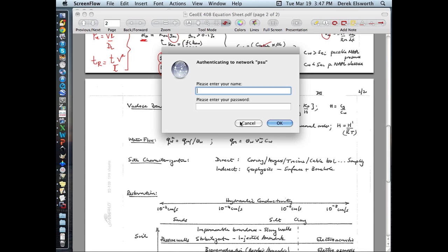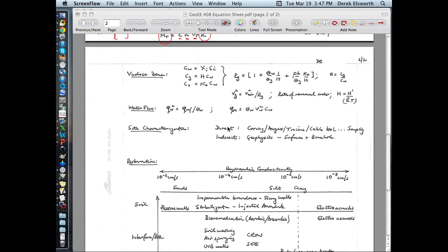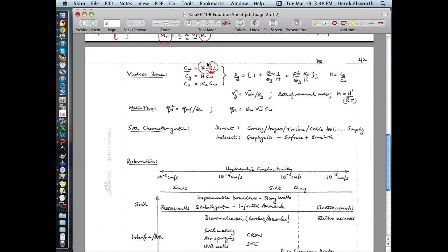So we also did it for the vadose zone. We looked at transport in the gas phase. We also defined the relative concentrations in terms of Raoult's law as a function of the individual solubilities and the mole fractions. We defined the gas concentration as a function of the aqueous concentration through this non-dimensionalized Henry's law. In fact, the definition of Henry's law coefficient is just the ratio of the gaseous and the aqueous concentrations. And we defined the solid concentration as the equilibrium concentration with the aqueous concentration just through the distribution coefficient.